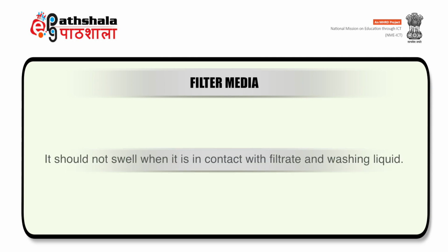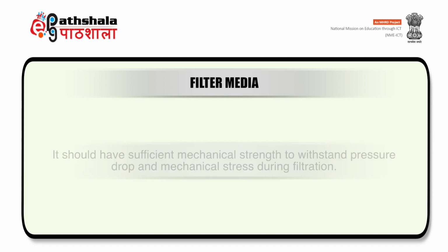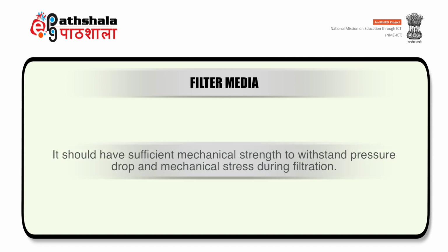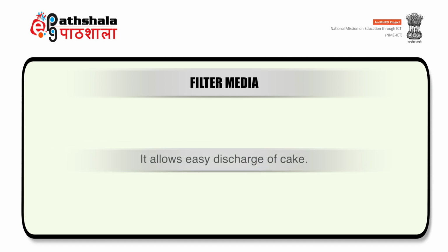Fourth, it should not swell when it is in contact with filtrate and the washing liquid. It should have sufficient mechanical strength to withstand the pressure drop and mechanical stress during filtration. And lastly, it should allow easy discharge of the cake.